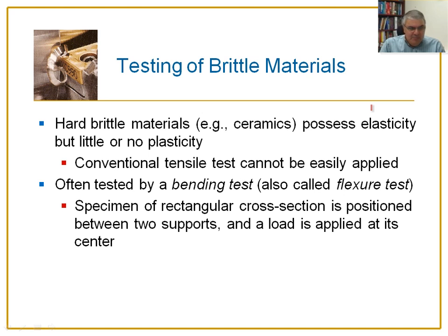So how do we test brittle material? If we can test the ductile material using the tensile testing, how can we test brittle material? The hard brittle materials, for example ceramics, possess elastic behavior, but they have little or no plasticity. So they yield up to a point beyond which they pretty much fracture or break. So conventional tensile tests cannot be easily applied to brittle material.